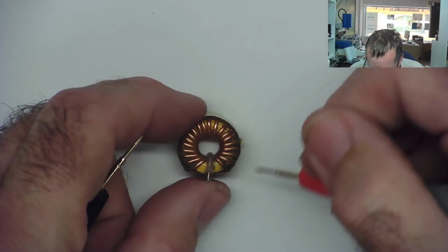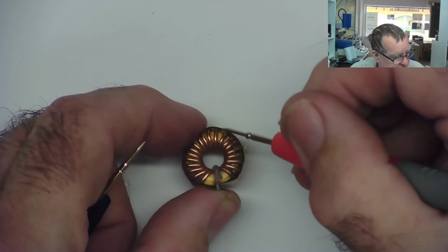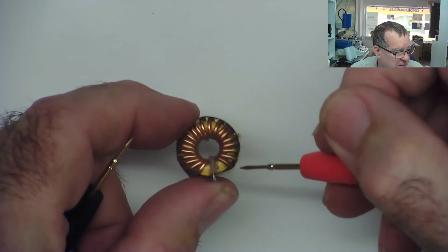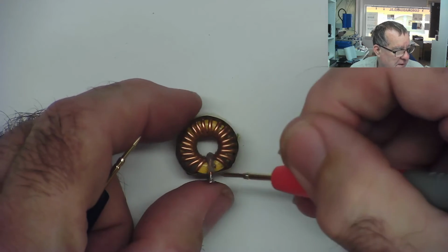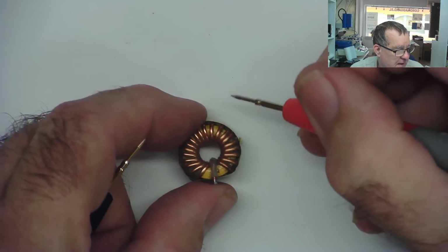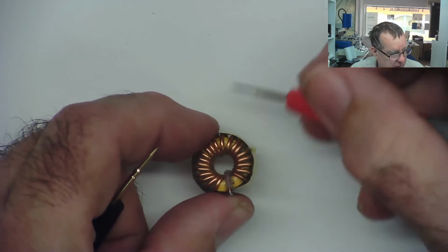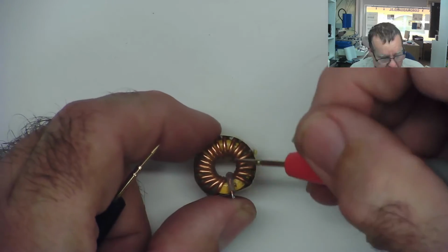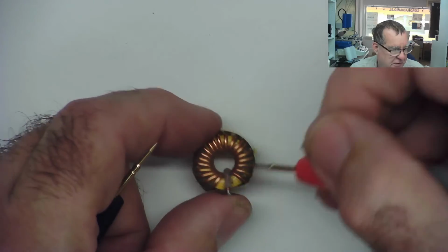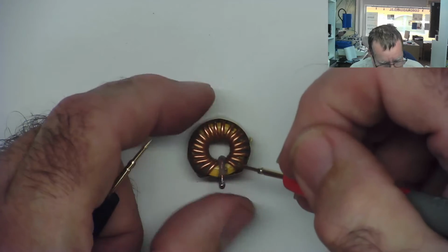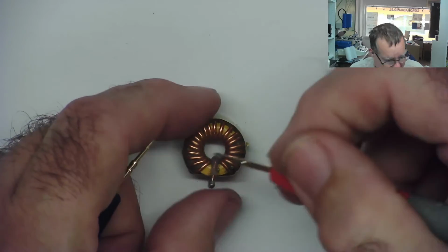But in fact, if you have a shorted turn, that turn effectively becomes a secondary winding, which is short circuit. And when it tries to magnetize the coil, it also induces electric current back into that shorted turn, which will pass an infinite amount of current. So it reduces the magnetic field, how much it can magnetize. It reduces the impedance of the inductor. So that's the other way they can fail.